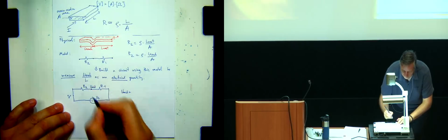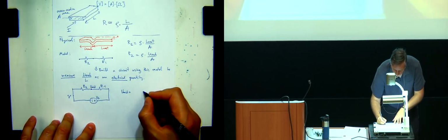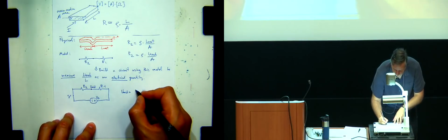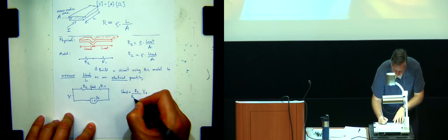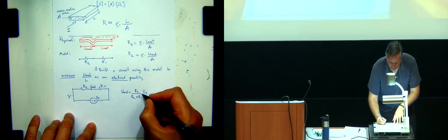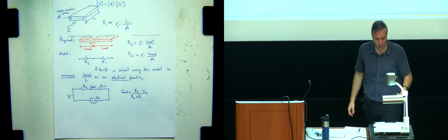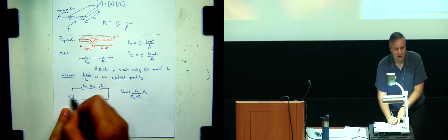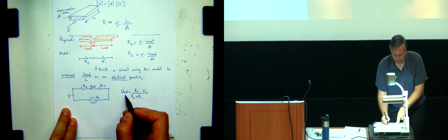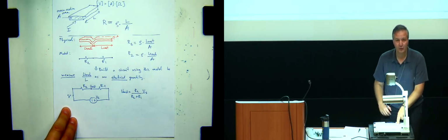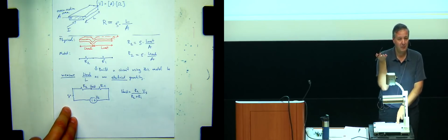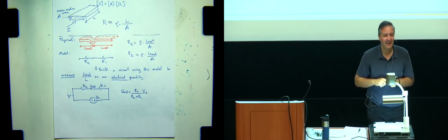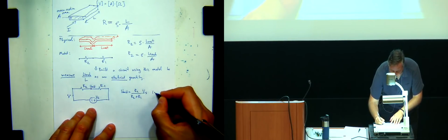Sorry, this is R2. Okay, so this is it. R2, U mid. U mid really means U mid minus 0. Really means the voltage across this R2, right? That is equal to R2 over R1 plus R2 times Vs. Where did you come up with that? How did you... You're like a Jedi, some sort... Okay, so that's the same circuit. This is a voltage divider.